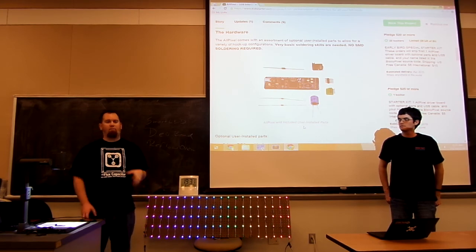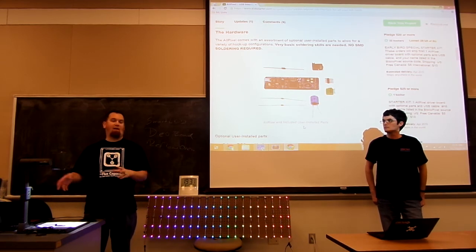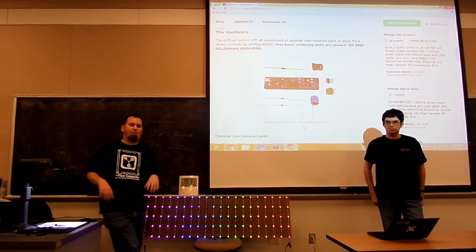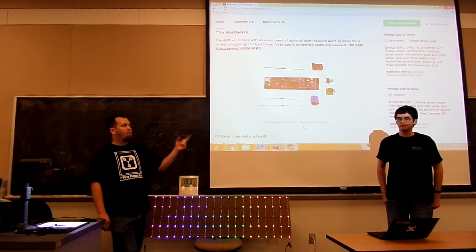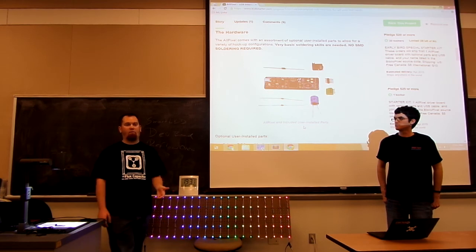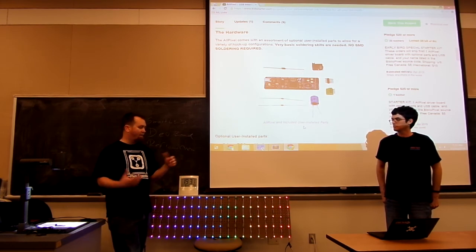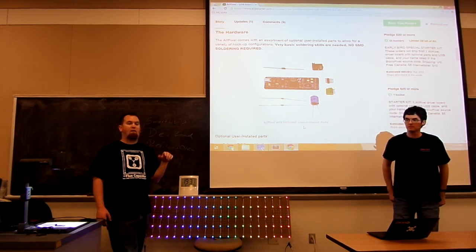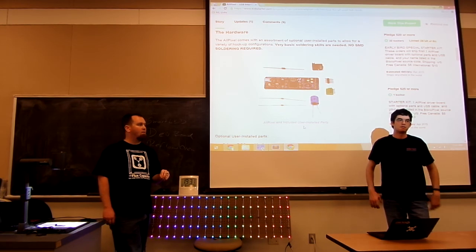is really slow. Before this we tried FTDI, which, forget it, it was like 15 kilobytes per second. We'd get 5 frames per second or something off the rate of this. The standard core libraries, you're talking about 60 kilobytes per second, which is still no good. With this, I've actually tested it at a full 1.1, 1.2 megabytes per second throughput. So I've got the 24 by 24 matrix, and I can push 100, 150 frames a second, again depending on the animation.